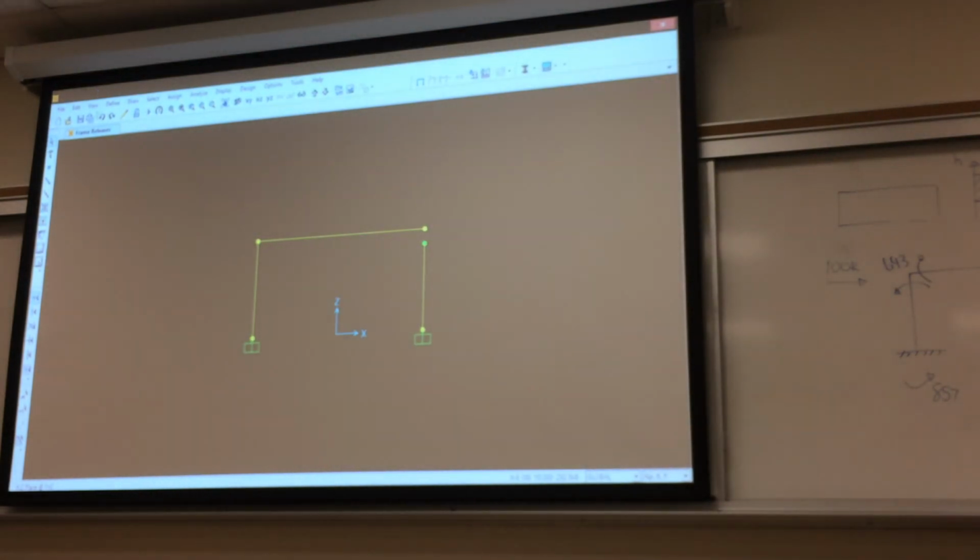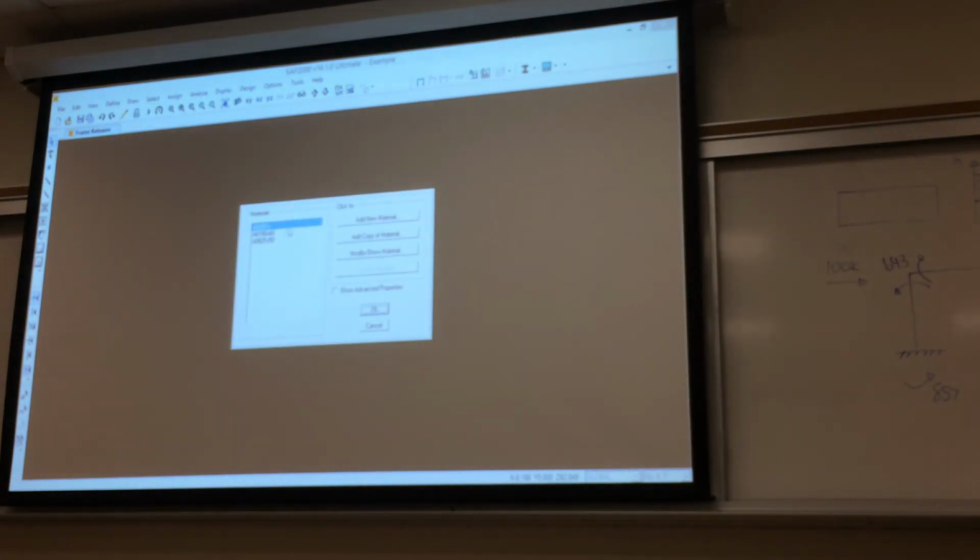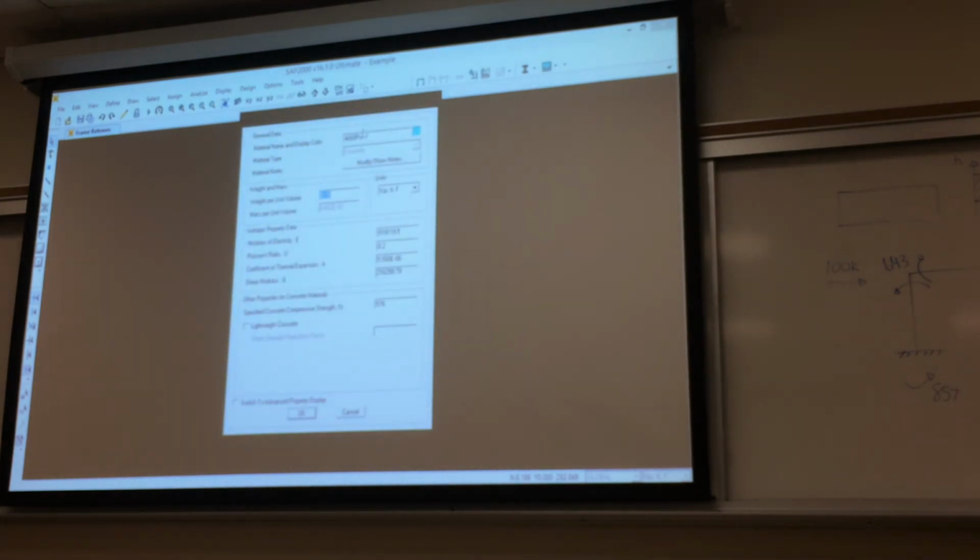And also one thing before we do that, we should define materials. I didn't set the E for this. E for this material is 4110 KSI. So I'm just going to modify the standard concrete. 4,000 PSI is what SAP calls a normal concrete. You can come in here. I'm going to change my units to kips and inches temporarily. And for modulus of elasticity, SAP defaults to 3605, which is what you get from the design equations for 4 KSI structural concrete. But we're going to use 4110 because that's what came from our material models for this particular section.